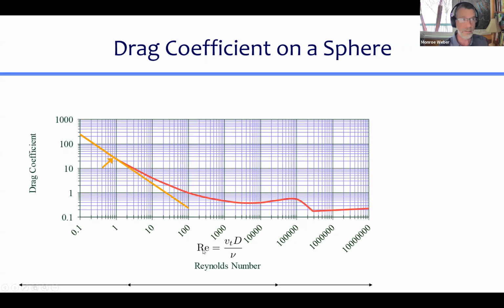This bottom Reynolds number is V times D over nu. So V is how fast the car is traveling. D is some width of the car or height of the car. And you're comparing that with a golf ball. So the Reynolds number for a car is higher, given it's traveling at a similar speed.